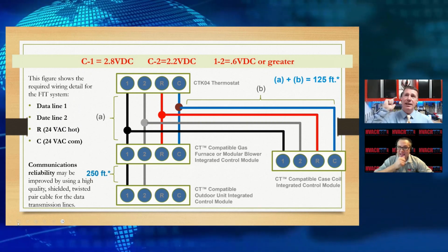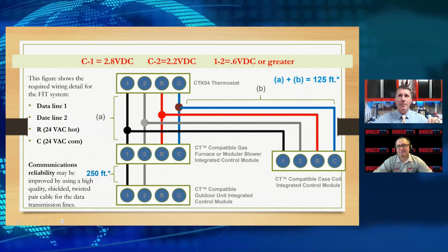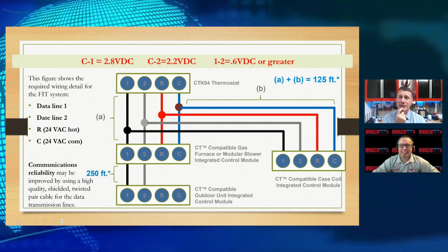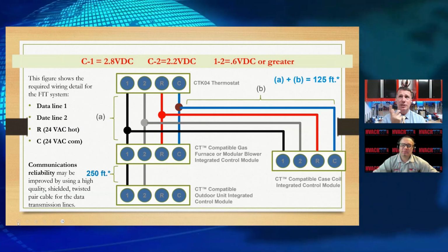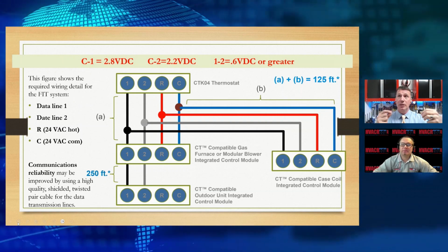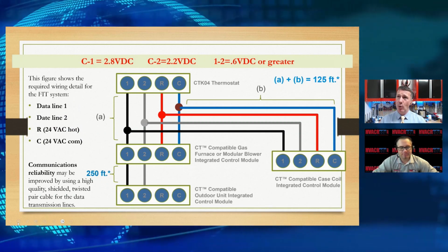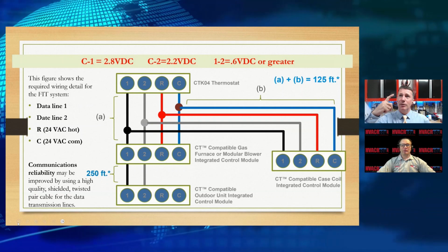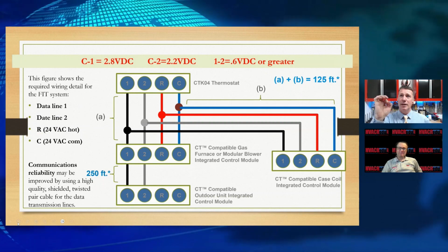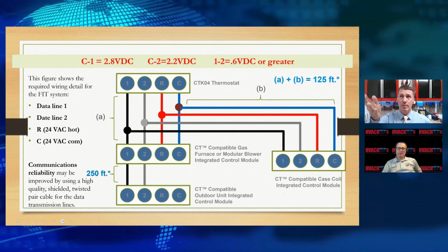So I had a technician that called me and said, "Hey, I've got good bias voltage at my indoor, at my thermostat, and my EEV, my outdoor unit. I've got some janky voltages and my bias is not right." I'm like, "Well, that's really interesting. Let's check your voltages to ground," and they were low at the outdoor unit. So I had him disconnect the wires from the outdoor unit and check the wires going to it. The wires were good. As soon as we connected it to the outdoor unit, the voltage dropped. I thought, well, maybe it's a board, or is there something else? Let's go check all of our ground. And we found a corroded lug inside of the disconnect that had poor connection. So the path could not make it back through the electrical panel to the indoor unit. The reference point was bad.